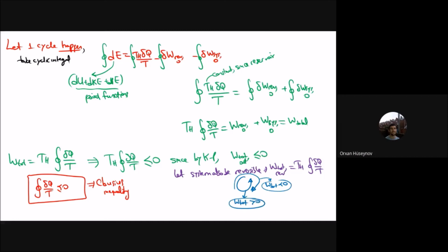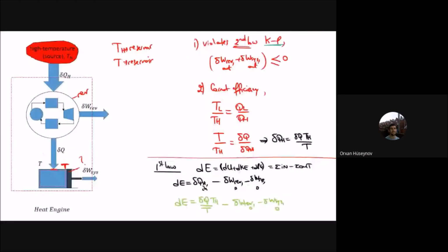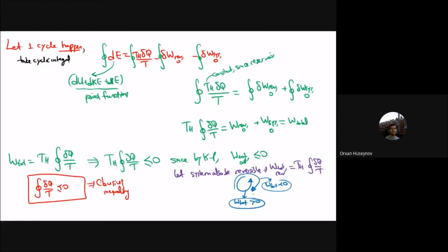But for the Kelvin-Planck statement, it is impossible, because this one violates second law. It doesn't matter whether it is reversible engine or irreversible engine. Any device that violates second law, that's all, it's finished, okay? Therefore, we cannot have positive work output in opposite one. It will be always either negative or 0.